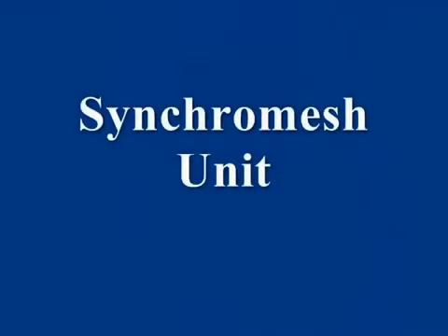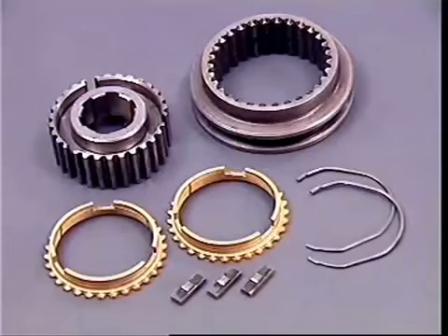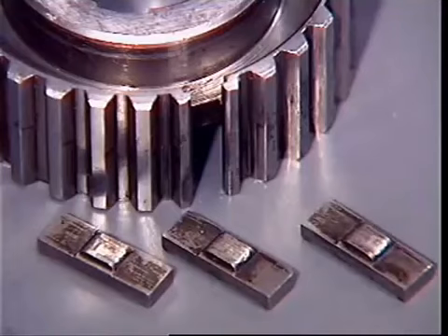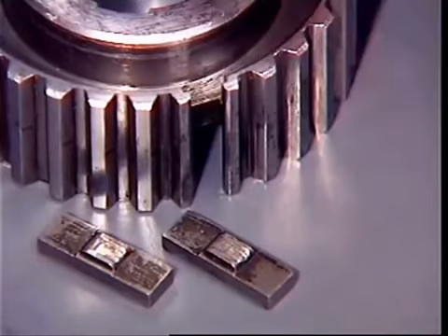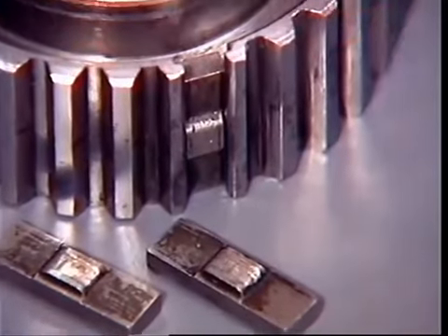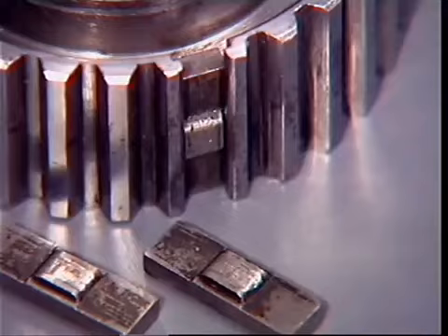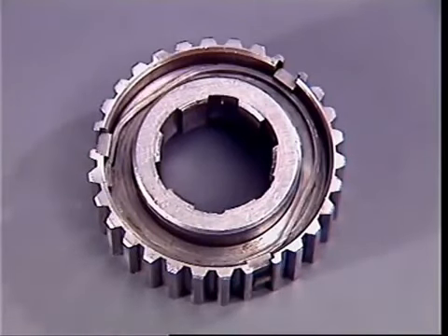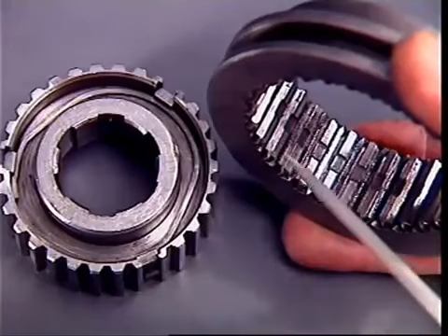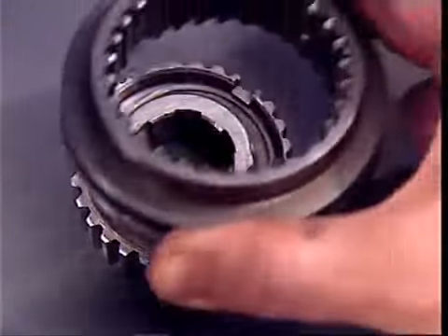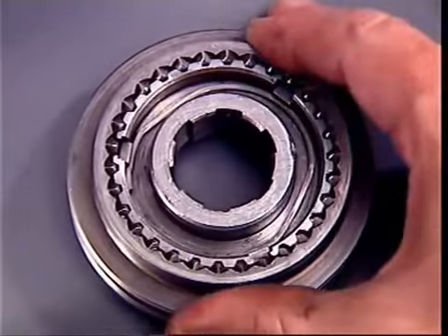A Borg-Warner ring type of synchromesh unit is commonly used to synchronize the speeds of two gears before engagement. 3 metal inserts with a ridge fit into slots in the hub. A radial spring at each end holds them out, so that the ridges locate in a groove inside the sleeve and hold it centrally on the hub.